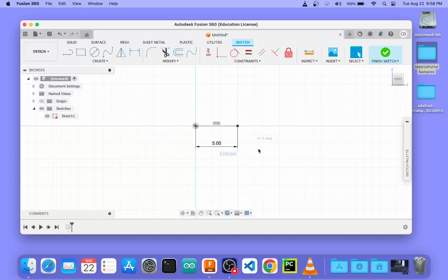I'm going to hit the L key again, and I'm going to get to where I've got the point on the end of my first line selected, and I've got a couple of options here. I'm going to put it at 5 millimeters. And I'm going to say it's 135 degrees. Let's try 45. Okay, 45 degrees. You'll notice the degrees are referencing the axis. That's actually not what we want to do. So I'm going to say it's 5 millimeters. That little lock means that it's dimensioned. It means that that is set. I'm just going to put it somewhere off in space. Once it gives me the option to make another line here, I don't want to do that. I'm going to hit escape.